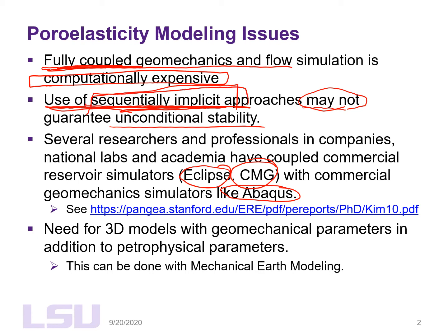And there are several approaches, four main approaches: fixed stress approach, fixed strain approach, then you have the drained splitting approach, and the undrained splitting approach. And of those four, the fixed stress approach is the most stable.